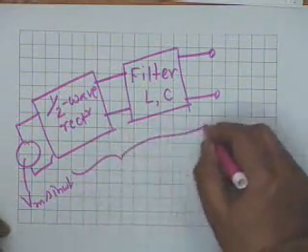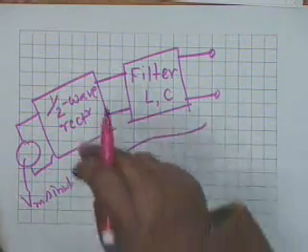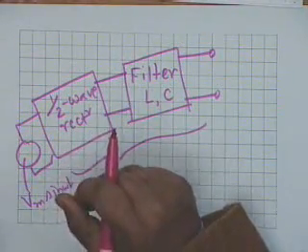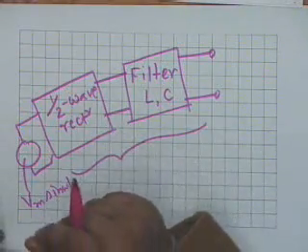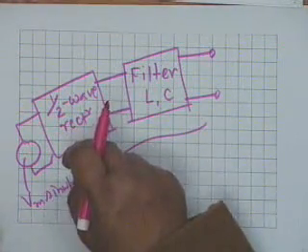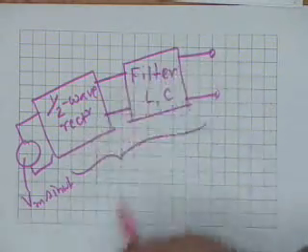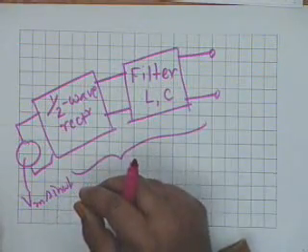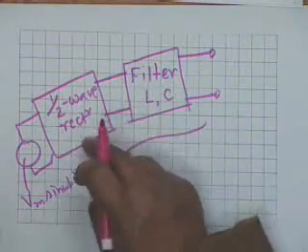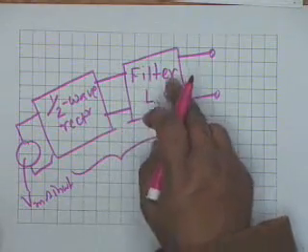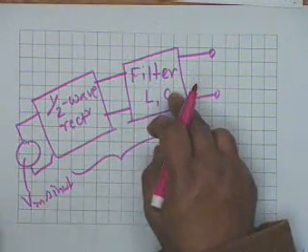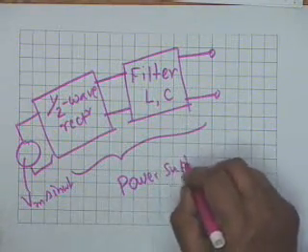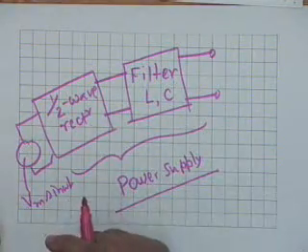And this combination of a rectifier, as you will see later, a rectifier could be half wave or full wave. We can use more than one diode in a connection, such that the negative half is flipped to become positive, and the other half is also utilized, alright. So, any rectifier connected to a filter to filter out the AC or the ripple, the total combination is called a power supply.